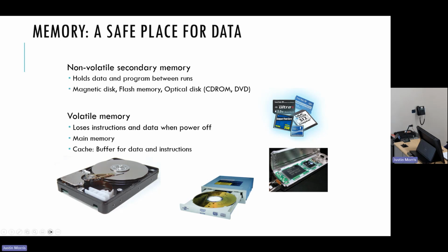That is why we consider it non-volatile, because they do not need to be powered to keep their data. Turn the computer off, the data is still there. But volatile memory, as soon as they lose power, they start discharging and everything becomes zero. So this is used as DRAM, which is your computer memory, as well as SRAM, which is for your caches and your registers on the processor.